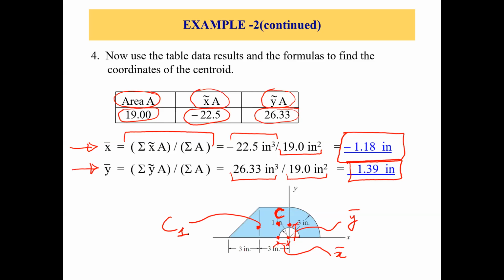It has to be somewhere in the center. Point C looks to be in the center, but point C1 doesn't. So if we get something like C1 as the centroid, then there is something wrong within our solution, maybe some multiplication error or some formula error, so that's why we are not getting the correct answer. But if we get something like C, then we can say it seems right.